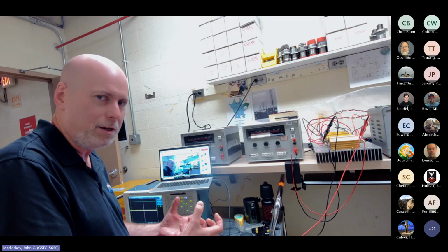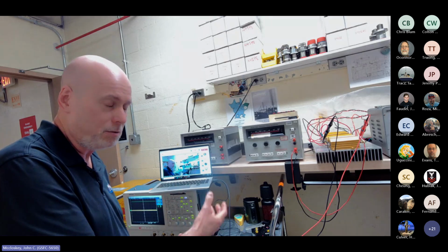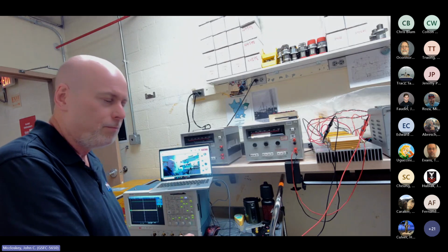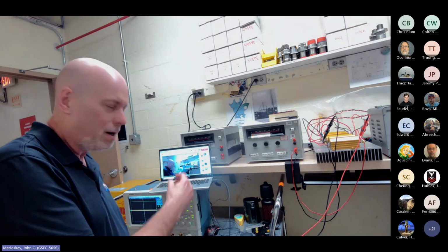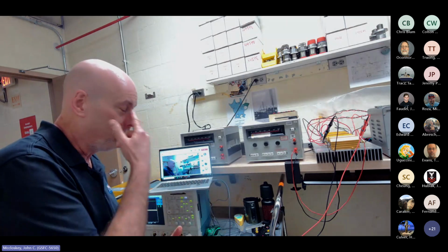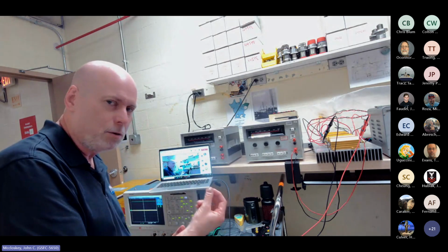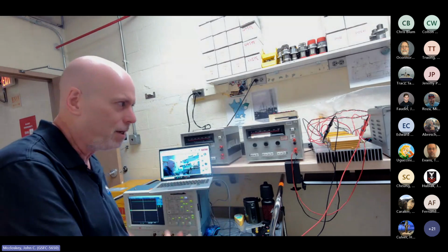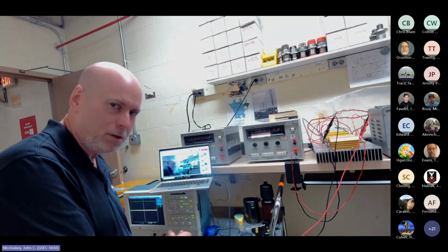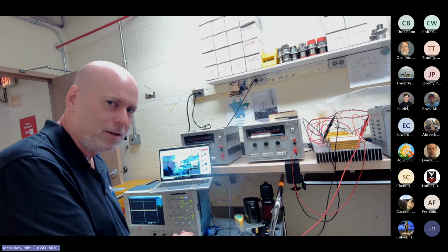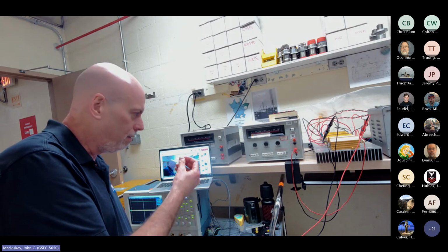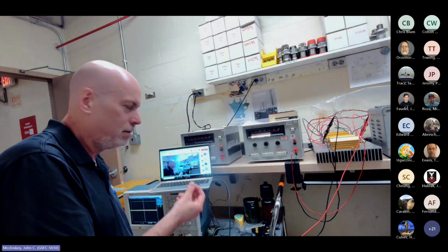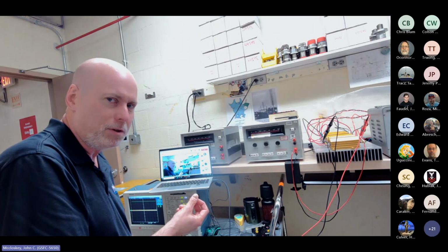You don't know what the impedance is of your EUT unless you've specifically characterized it. And you do want to monitor the signal that you're injecting, but you're going to have less control over what it looks like depending on the impedance of the EUT at any given frequency. So the pre-calibration step is extremely important.